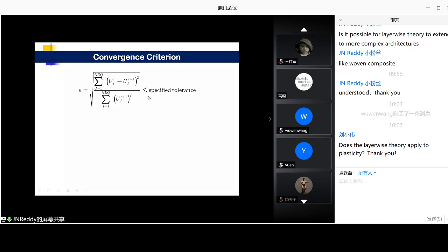Okay. So by the way, if we set the tolerance at 10 to the minus 6, it may not converge at all. But it is really academic to say 10 to the minus 6. See, 1% error or 0.1% error means 10 to the minus 2 is enough. So you don't really try to unnecessarily force your code to go into iteration, and it only helps you get fourth or fifth decimal point accuracy, which is only academic.